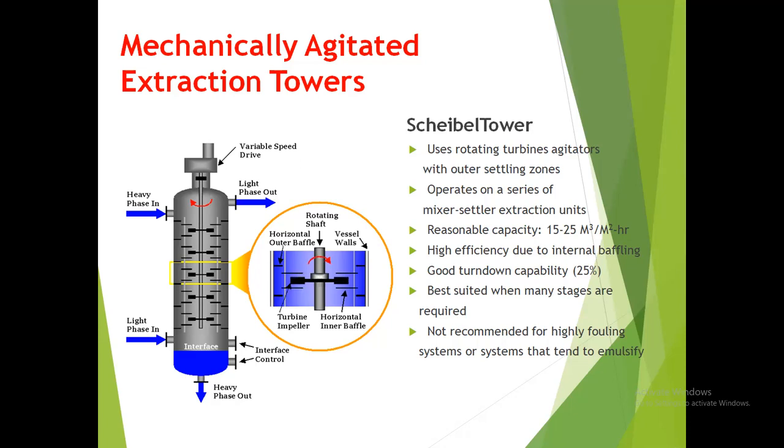Now, what is the best application for such a special type of extraction tower? It is best suited when there are many required stages for the extraction to achieve its recoverability. If we need a high recoverability for our extraction, then this is the tower, this is the extraction equipment to use.